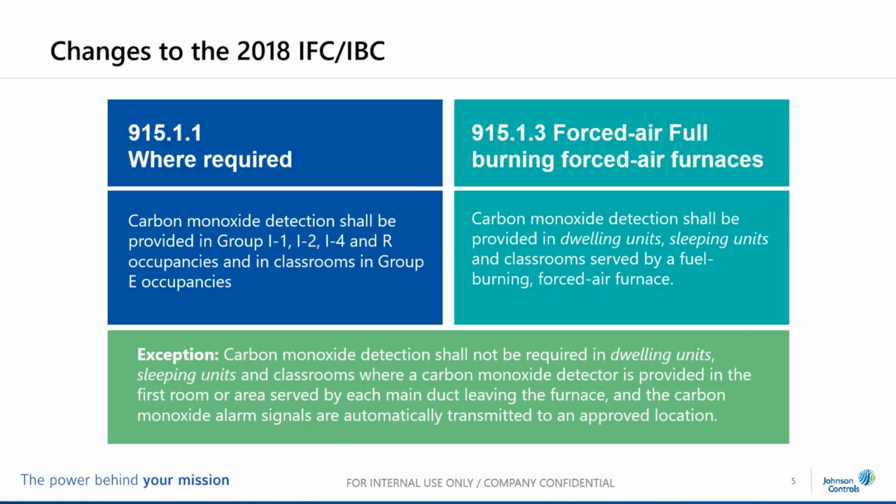If we back up for a second, we need carbon monoxide detection to notify us when there is some type of thing going on with a fossil fuel burning appliance, whether it be an HVAC, a water heater, could be a vehicle if we have an attached garage, can be a fireplace if the fireplace is burning wood, fossil fuel burning or natural burning materials. A byproduct of incomplete burning is carbon monoxide.